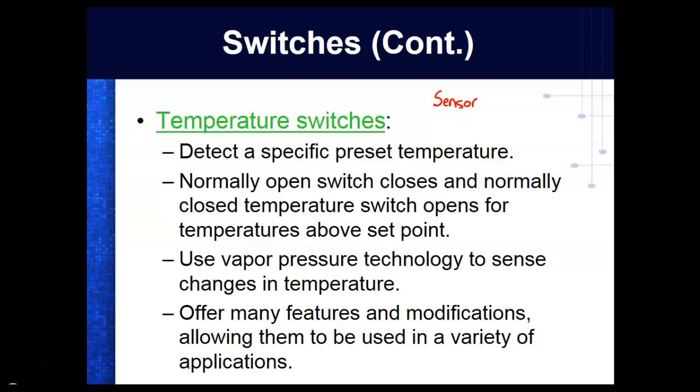What they used to sense the temperature was just a bulb with air in it. When the glue would heat up, the air would expand and go over there and trip a pressure switch. So it was a temperature switch, which was really cool. So that's undoubtedly what this is talking about. We have all different types of ways we can sense temperature.